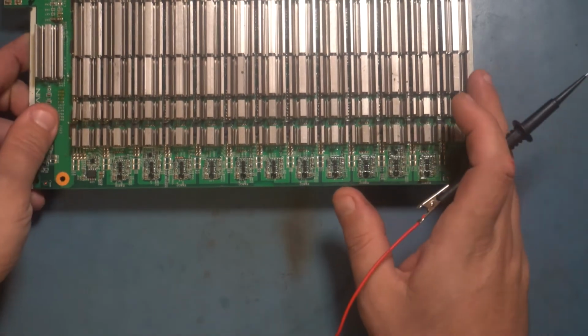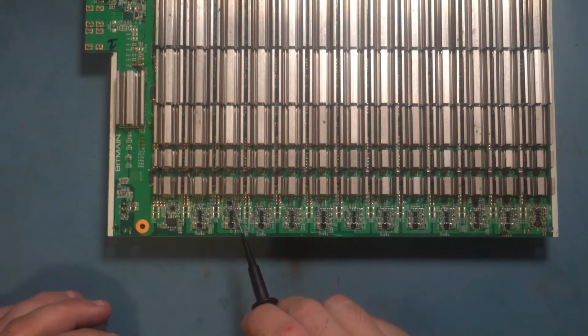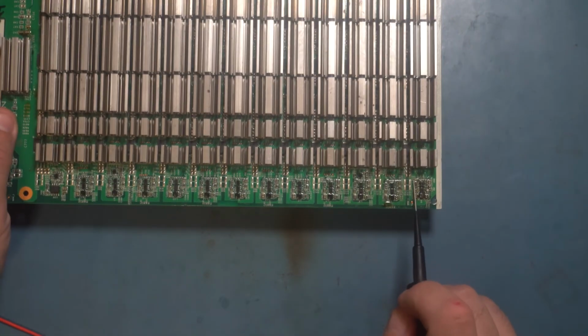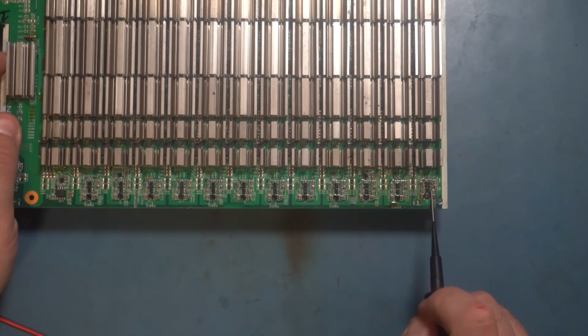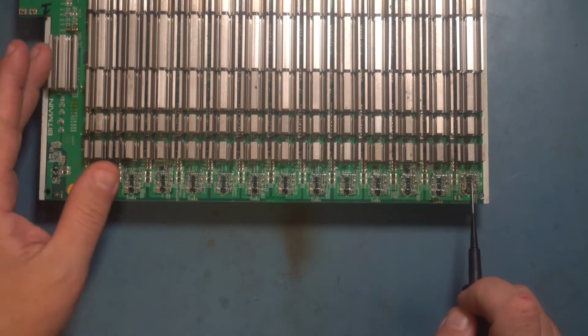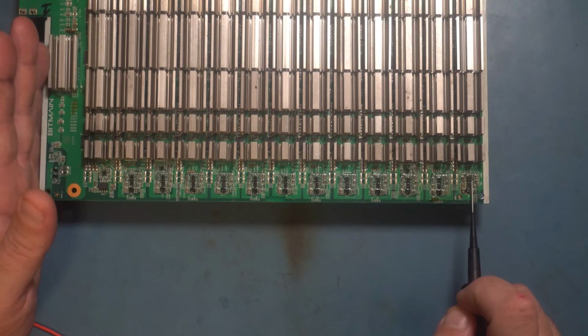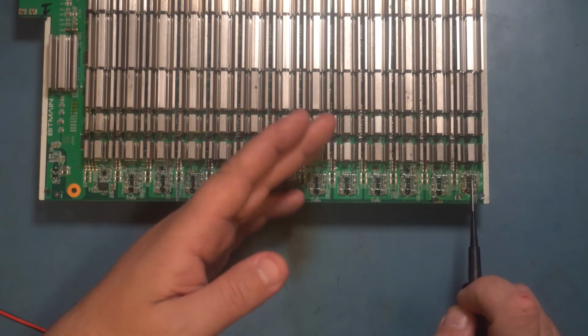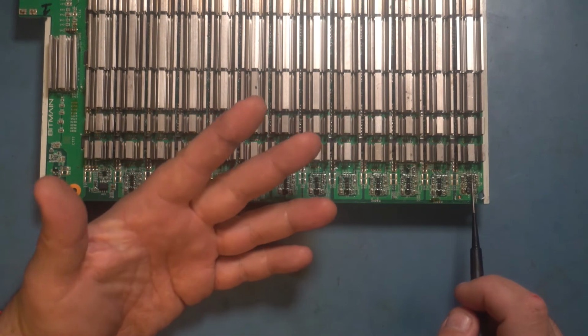And so this is the same thing for each of them. So that's all fine and dandy, but what happens when you get to the end of the board? So as we know, if we are at the very beginning, so again, if we're in domain 1, and we're looking at regulating 1.8 volt, well, it's easy because we got potentially up to the full board voltage to work with, right? So we got all the way up to 24 volts that we can regulate all the way down to 1.8.